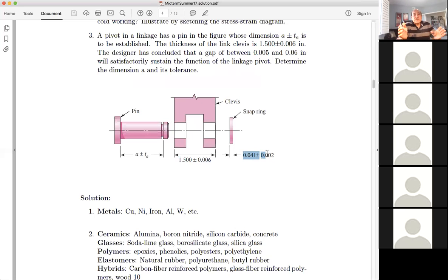So these come from the manufacturing step, that the clevis and the snap ring, you produce it in thousands and millions, and then you have statistical analysis. Somebody comes and does the measurements and then gives you a Gaussian distribution, and that is the standard deviation that is defined, right? So now you want to order a pin from another manufacturer. So the manufacturer is going to have to certify that the pin has an average value and a standard deviation.